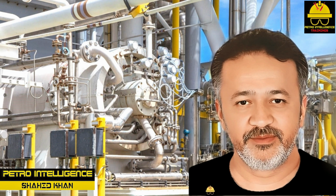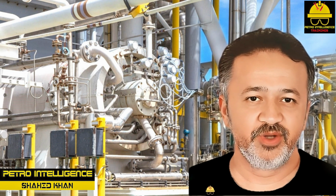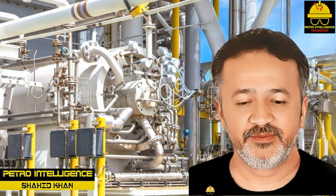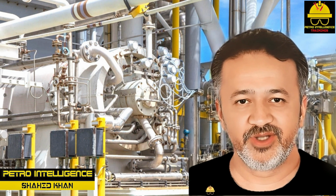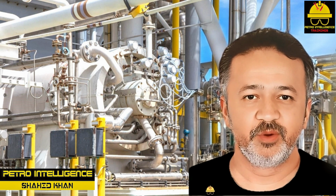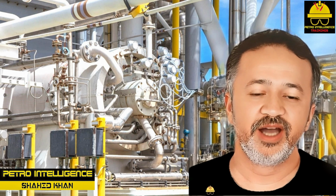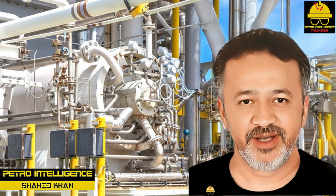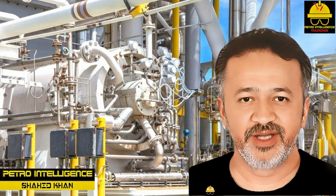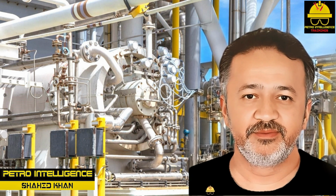Compression ratio. Compression ratio is defined as the ratio of discharge pressure, PSIA, to suction pressure, PSIA. Frequently, the desired discharge pressure is very high, over 100 times that of the inlet pressure. When a gas is compressed, the temperature of the gas increases. If a gas was compressed in one stage to a pressure 100 times that of the inlet pressure, the gas temperature would be extremely high.